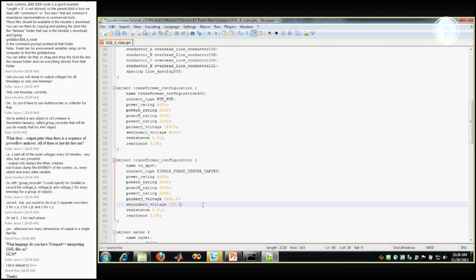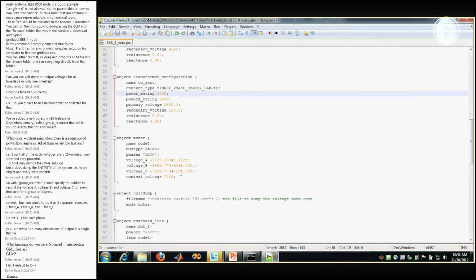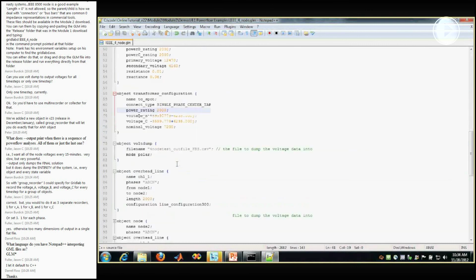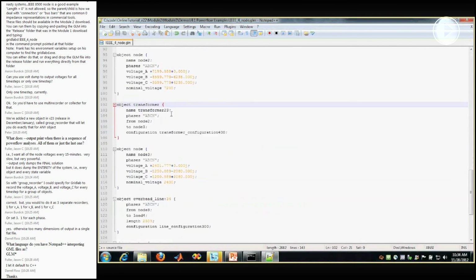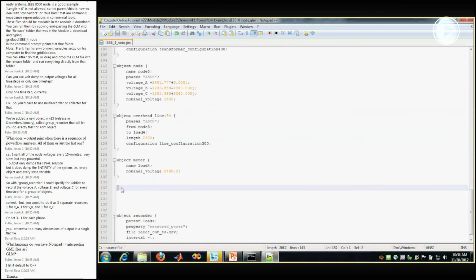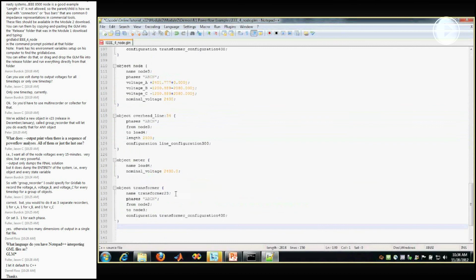And since this is a distribution system in North America, we're going down to 120 volts. We'll leave the resistance reactance the same just because. And I'll get rid of 2 of these. Rating. And now we'll go ahead and we'll steal the transformer just to change it, just so we have a template to work from. Down below, we have to give it a new name, otherwise it will yell at us.